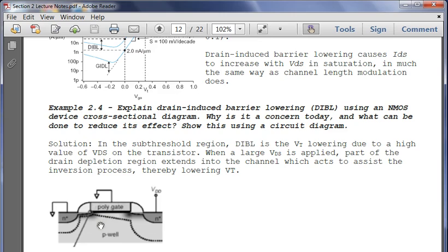So that's why when you've lowered the barrier, you've now increased drain source voltage. So tie this back up here. The drain source voltage increases because the barrier has been lowered, the amount that you actually need in order to actually create the inversion region, create the channel.